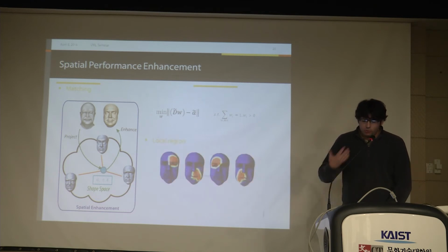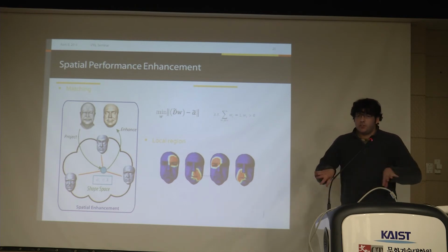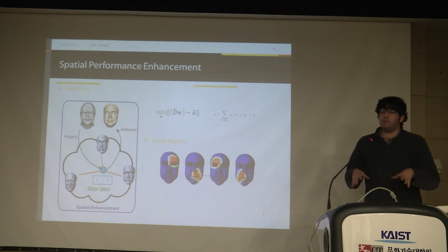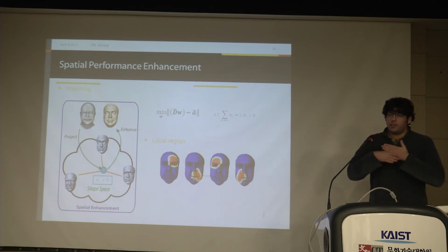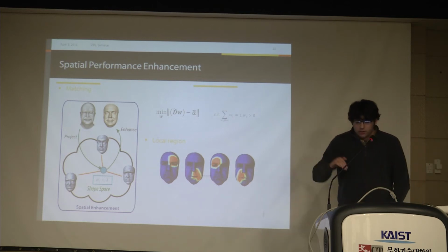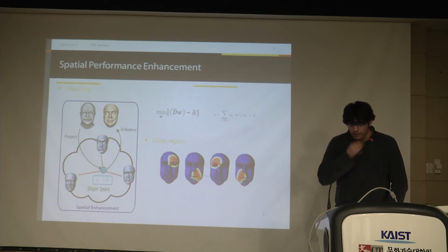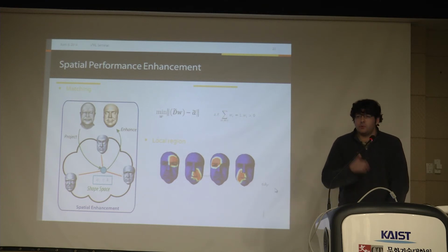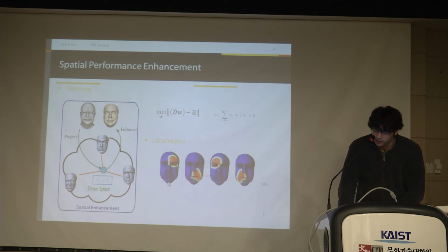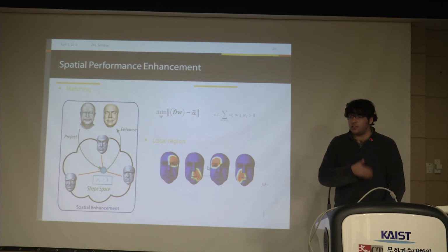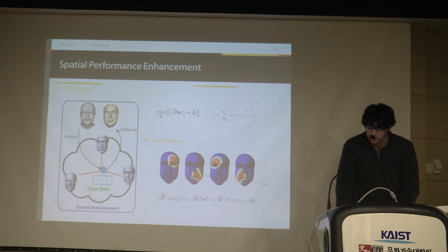The second part is that we want to introduce the concept of regions. It means that each region needs to be computed separately. But if it's computed separately, there might be some problems in-between regions. So they introduced the region weighting by making a least squares. Each region can be considered as a weight per triangle, so each triangle has a weight. For example, the triangle here will be 1 for region 1, but it will be 0 for region 2. So it's just a 1D vector, where each triangle has a weight. Then this can be introduced into the equation by this kind of list.